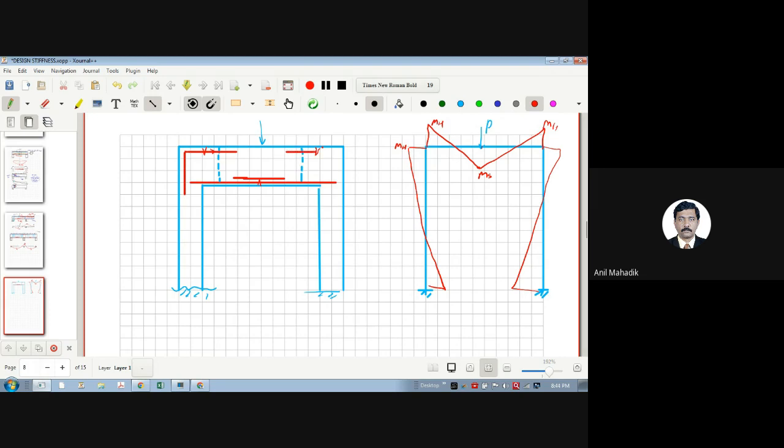Again here, ये bending moment है. So this vertical bar, which we can say is a single bar without any lap, is taking care of moment. This vertical will take care of M_h in column, and this horizontal bar will take care of M_h in beam.